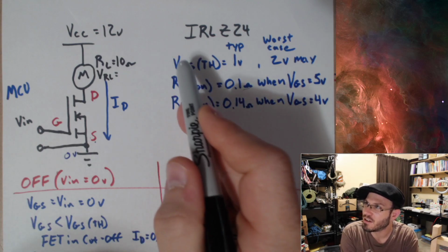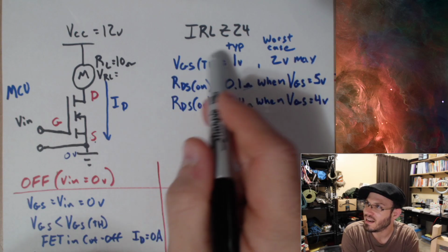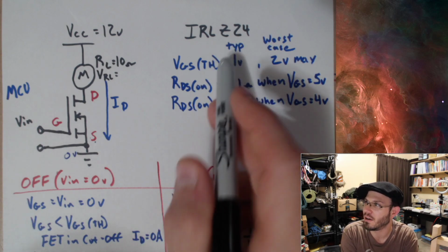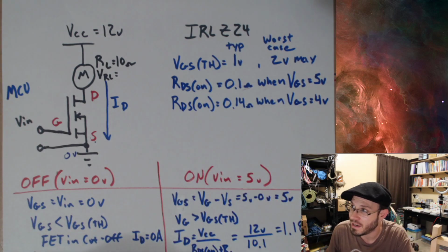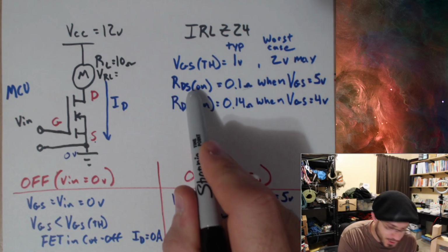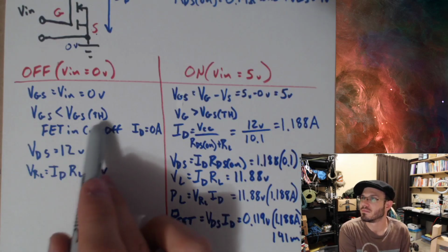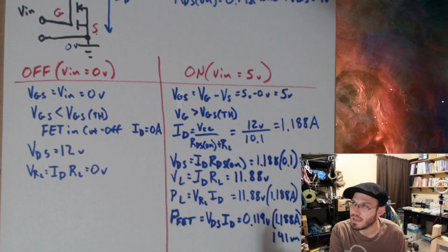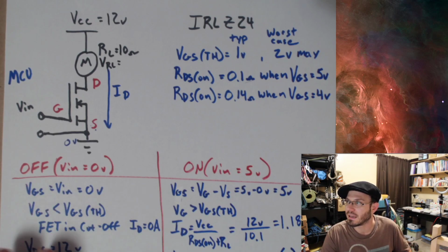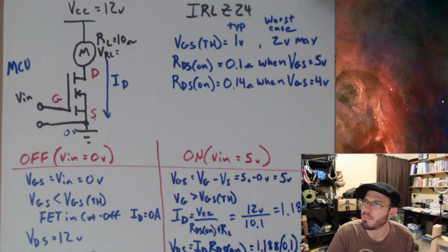If there's a V and there's a G and an S, it's the voltage between these 2 points. And then this TH is just the threshold voltage, some arbitrary number decided by the manufacturer that we must exceed. Same thing over here. The resistance between the drain and the source when the transistor is on. Okay. Don't get overly confused by the terminology, by these variable names. Okay.